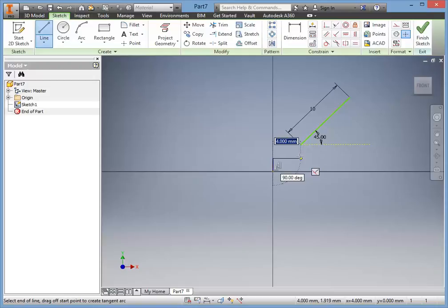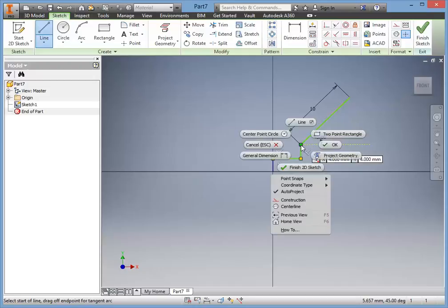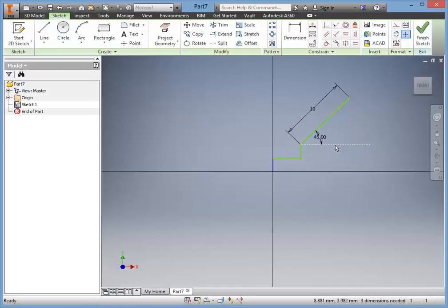And the reason for that is that Inventor helps you line up all the other items in your drawing so that they're with the same measurements. Once you've clicked, you'll know that the end of that line is directly beneath the green 45-degree angle line. So just connect them again with each other and you'll notice they're all chained together. Right click and you can click OK.